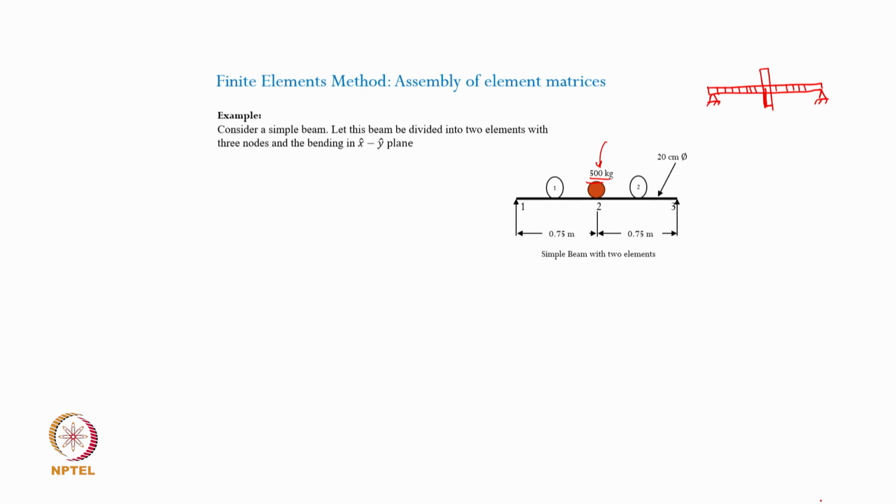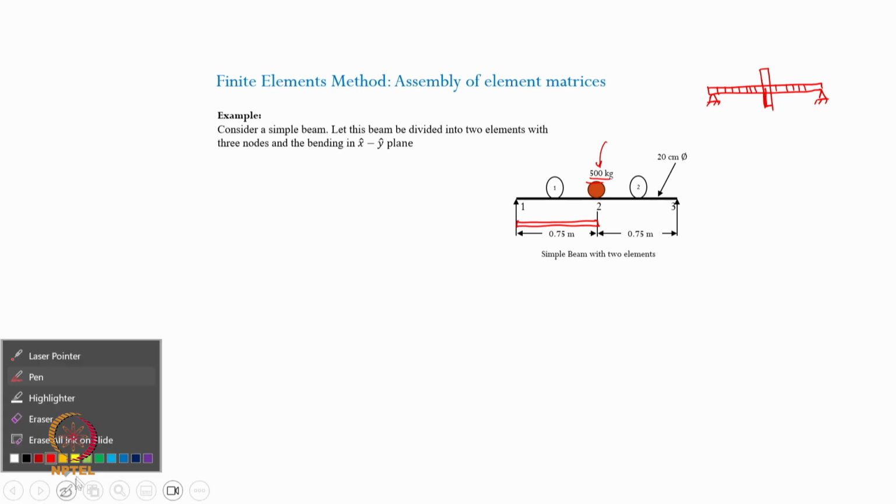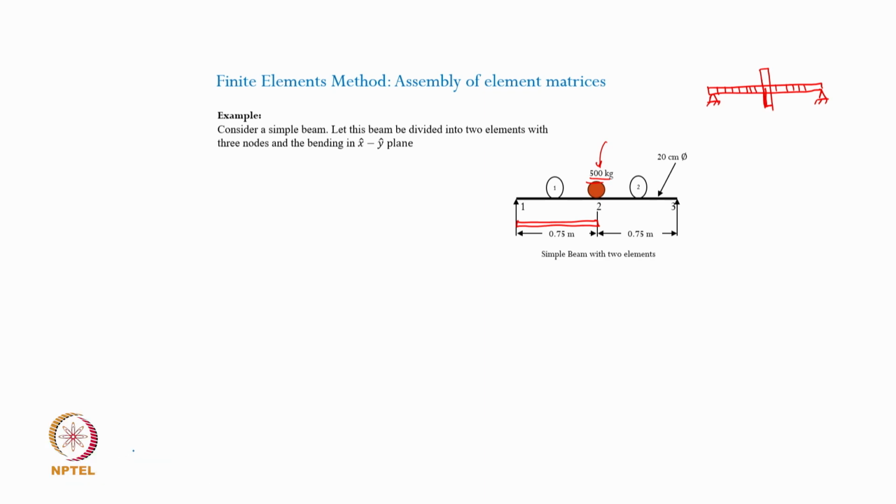Okay. So, as we discussed, the continua is discretized into two segments. One segment is here, which is the first segment, and the second segment is here. Okay. So, just two segments, two finite elements with their individual properties. In this case, because the disc is in the center of the span, the lengths are identical, and for the case here we also consider the diameter to be the same.